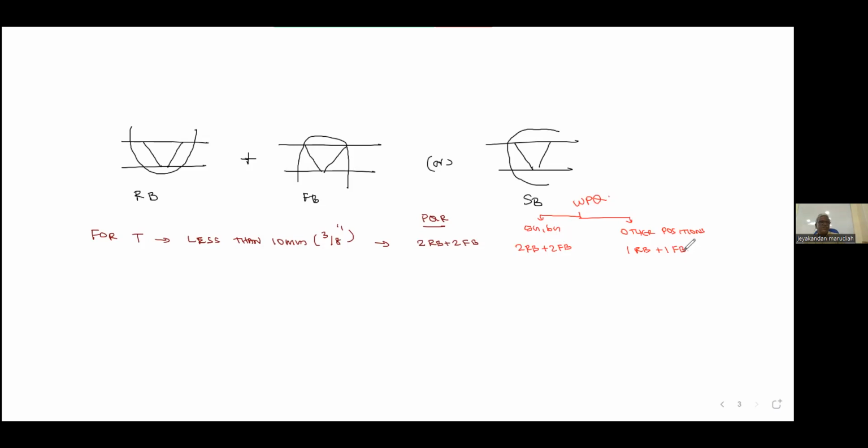Now, first, what are the positions we have? If you take a plate, if the plate is like this and the welder is welding, this is called flat 1G. Plate is horizontal, welder is welding: horizontal 2G. Vertical 3G uphill, 3G downhill. Overhead 4G. So plate has four positions: 1G is flat, 2G is horizontal, 3G is vertical, 4G is overhead.